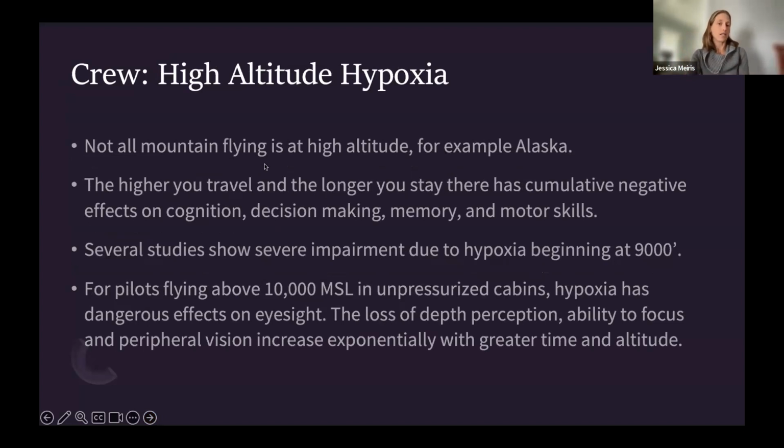And that can be a pretty serious situation pretty quickly in the mountain environments. And hypoxia, another concern. Not all mountain flying is considered high altitude. The Alaskan mountains are a great example. However, if you aren't accustomed to operating at any altitude, say you're from sea level, then hypoxia is going to be a major concern, even at what we would consider lower altitude mountains, say 3,000 or 4,000 feet.